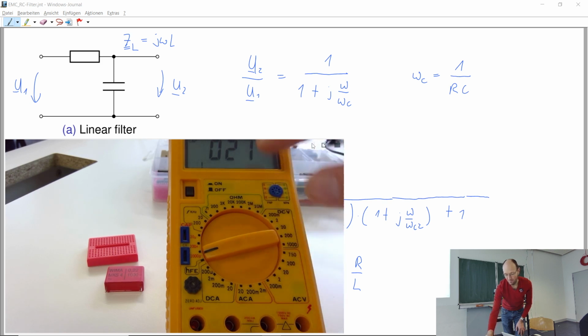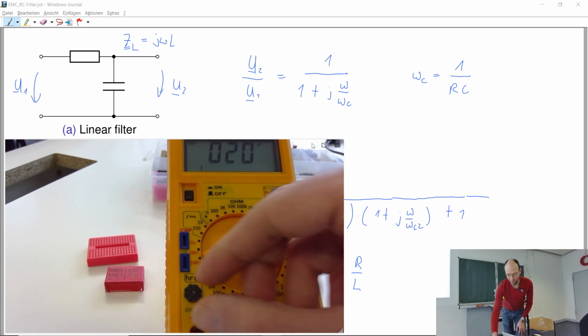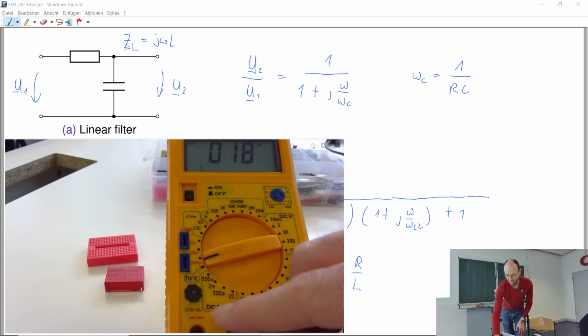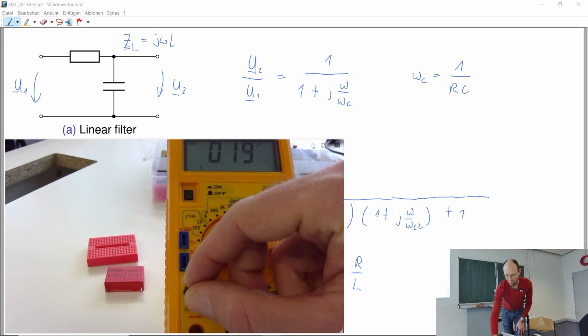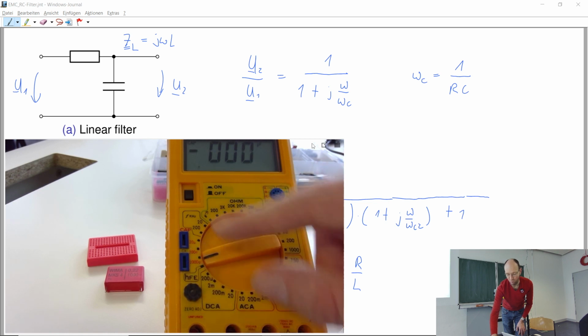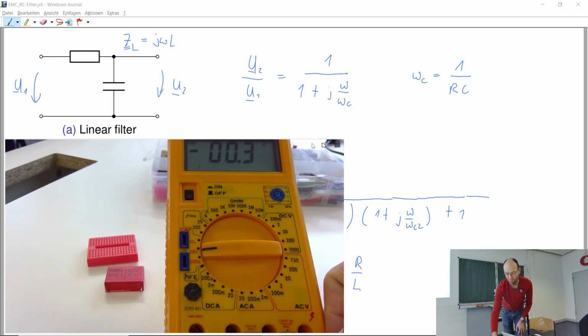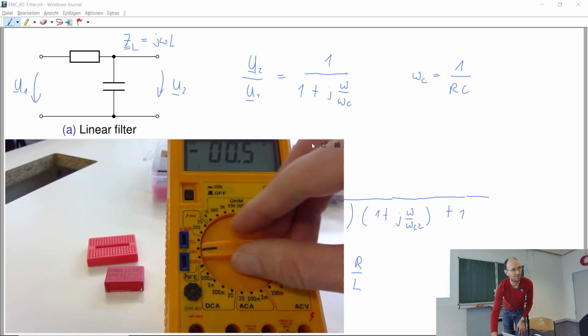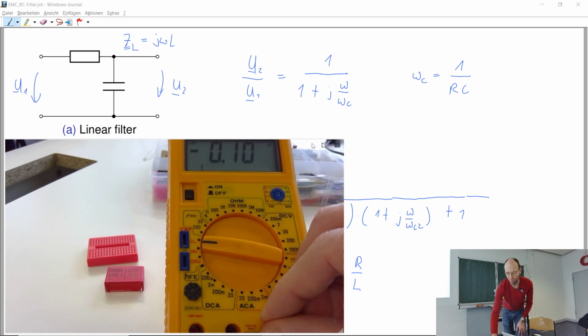And so even if nothing is connected there, it's measuring something. And what I've learned, and this is a nice learning, is you always need to compensate here. So there is this small knob, and with this small knob, you have to rotate until this shows 0. The problem is, if you compensate this range, this range won't be compensated, and this range won't be compensated.